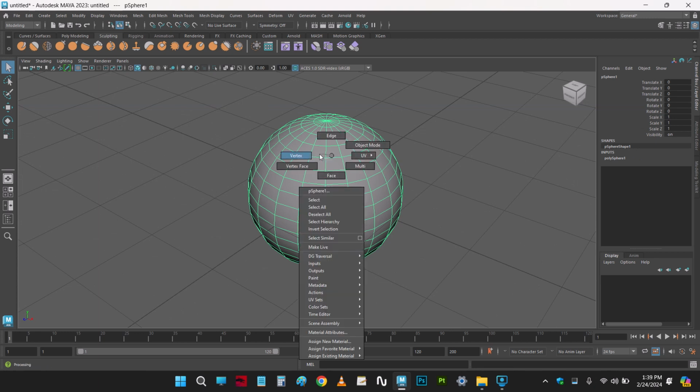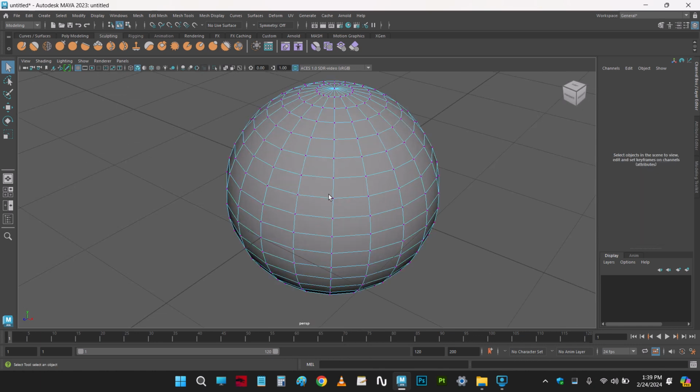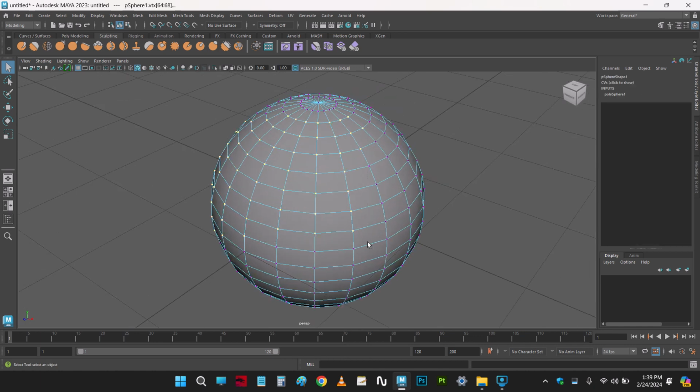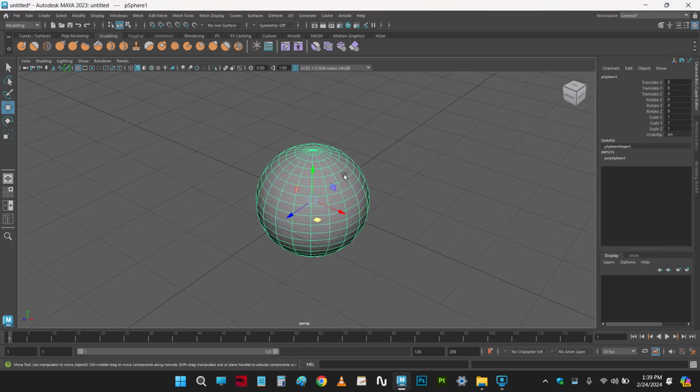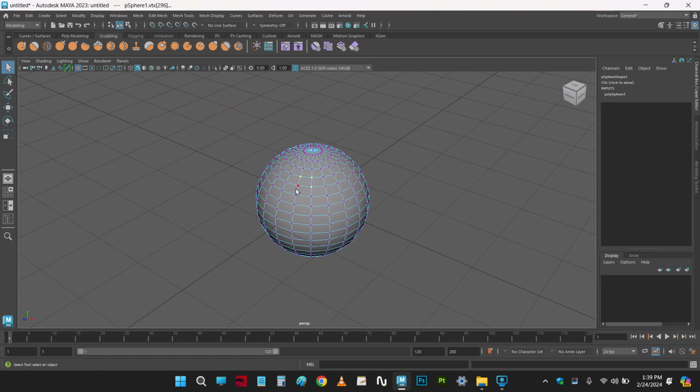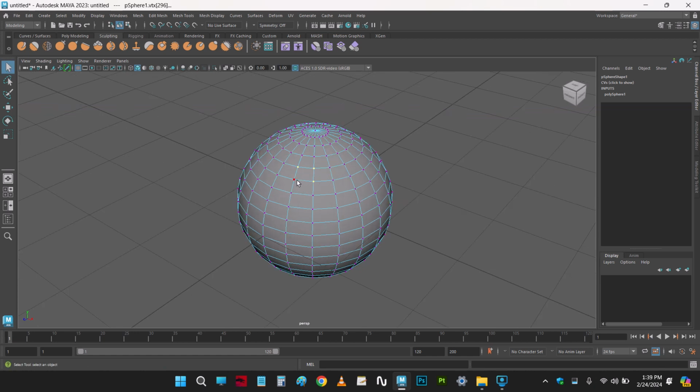Suppose you are selecting the vertices over here, I'll tell you what it is all about. All the vertices are getting selected, and then you press W, the move tool. Now you need to select the other vertex. Suppose this vertex is selected, and this vertex is selected. Now there are multiple vertices over here, the mesh is very huge, so n number of vertices. When you're selecting, you can see the gizmo coming in between. So for selecting, we can go to the select tool, and then the gizmo is hidden, and we can simply select it, right? So only this much of a difference.